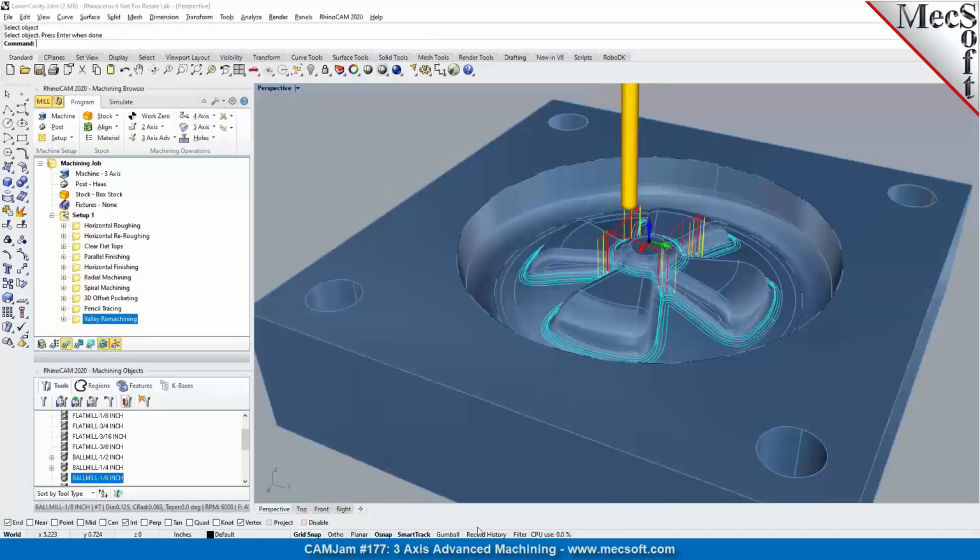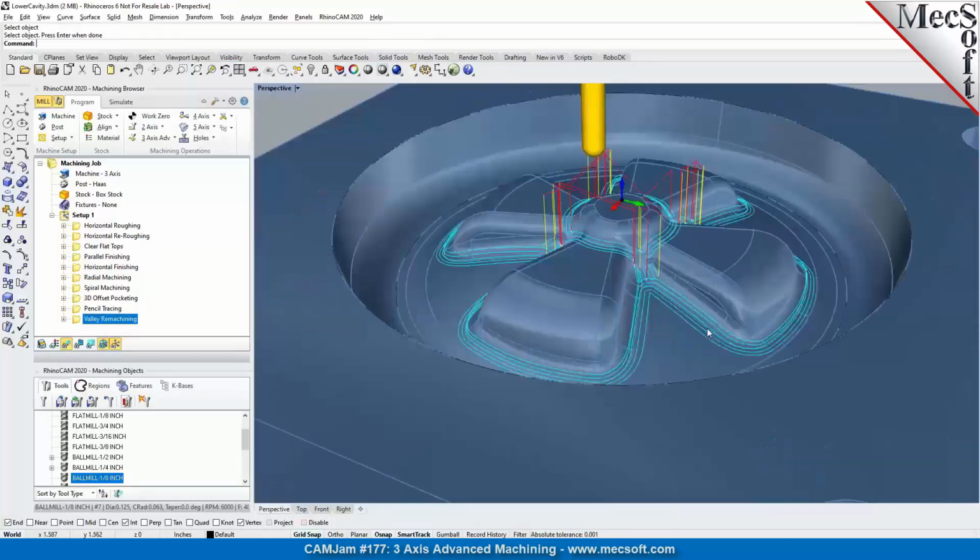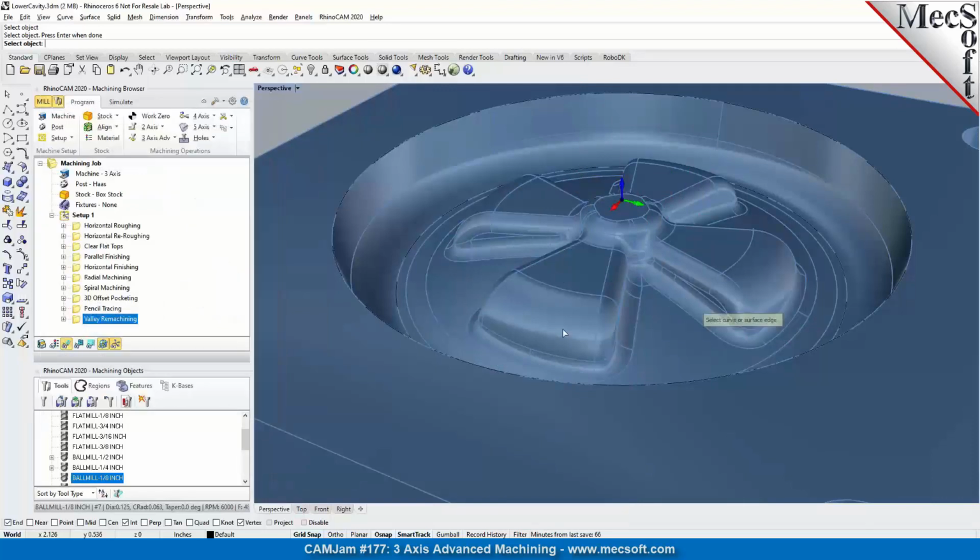Joe, I totally agree with what you said. And also one of the things that I could see is, if the radius of the tool is in close proximity to the radius of the fillet on a part, one of the techniques users can look into is a method called curve machining, or curve projection machining. So they can actually pick a curve at the base edge of the fillet, select the curve, and then drive it with a curve machining or curve projection machining toolpath as well.